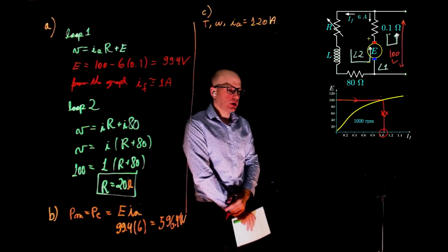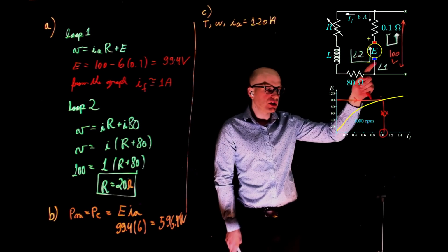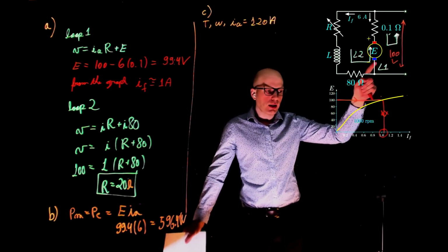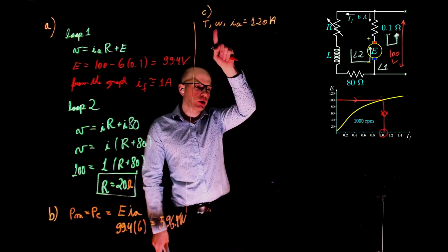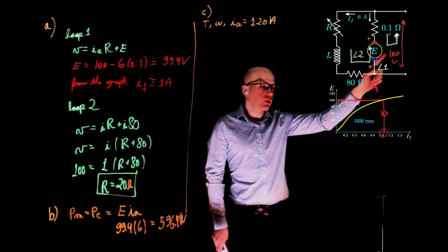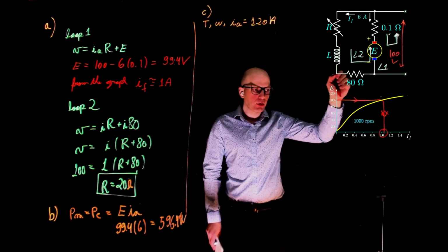What changes in the circuit? Well, if the current flowing here changes, E will change, and then the power delivered to the motor will also change. So if you're interested in power, torque, and speed, we first need to recalculate E. What is the new E now?